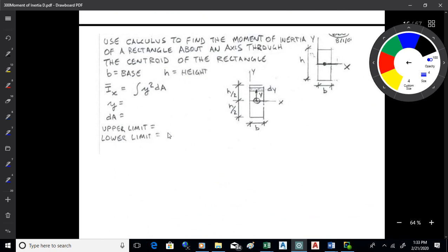All right, so let's calculate some moments of inertia so we know how to do that. Let's start off on page 720. Let's look at the basic definition. The basic definition is an integral, which means to add stuff up, of a distance from the neutral axis to an area, squared, times the area. Then you break that up into a bunch of areas, do that calculation, and add it up for all the different areas in the beam.